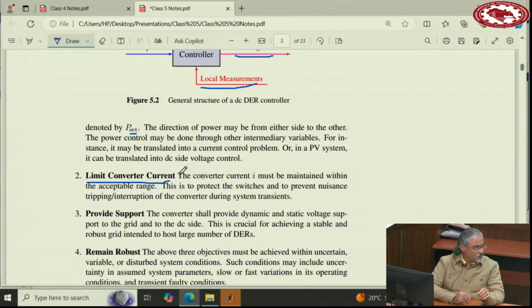A very short transient is alright, but not for any extended time. This is a major difference between power electronic devices and standard machines with windings, generators and motors, which in a transient mode can tolerate a huge amount of current, often several times the rated value. In power electronics, it is only a fraction of the rated, 20%, 30%, 40%.